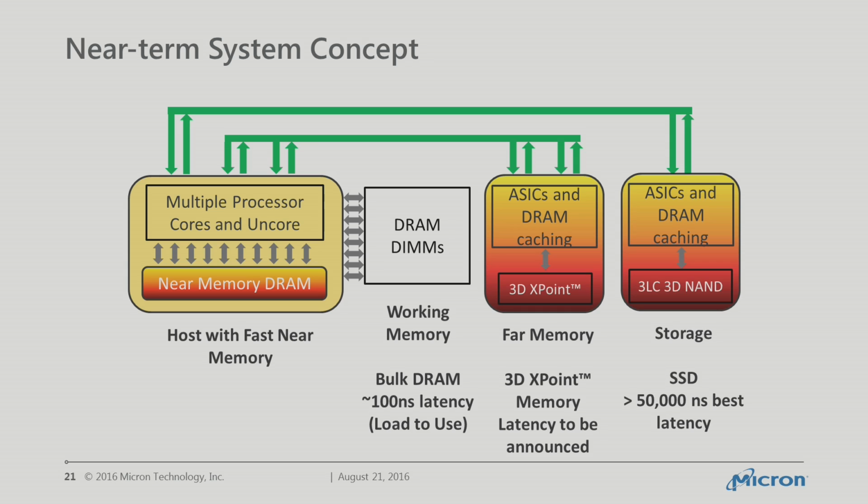Now, on the other side, if you were really paying attention, you saw in the very fine print nanoseconds, right? So I had a few products that use 3D crosspoint in that group, so sub 1 microsecond. But that's as fine grain as I'm able to go today. And then on the far right, we have today's 3 bits per cell 3D NAND. And actually, what I say here is greater than 50 microseconds, best case latency.